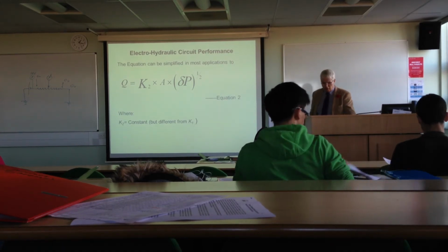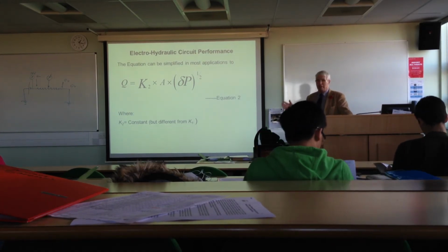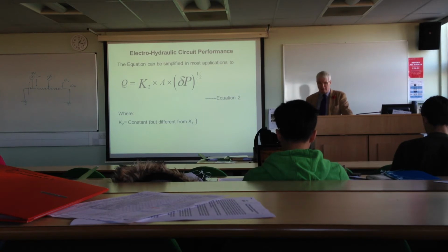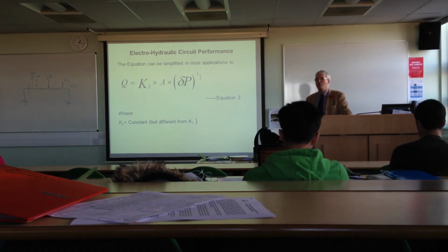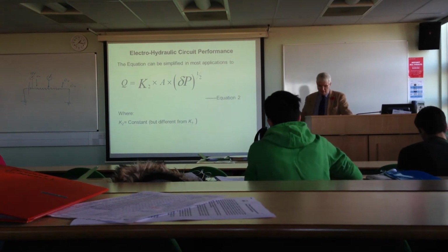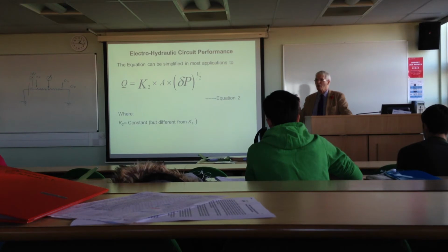Two weeks ago we got 4.53. You may not get exactly the same, because it depends which points you draw the line through. You can adjust it a little bit. But you can see that we were fairly consistent between 4.5 and 4.6 litres per minute per volt, but only for this 10 bar pressure drop.